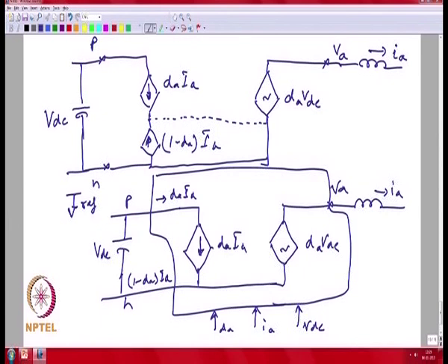And typically in control applications, you will have measurement of your DC bus voltage, you have your AC current measurements, your controller is actually outputting your duty cycle, and then you could actually incorporate a model such as this for the one leg of the power converter. So, instead of using the average value, now the value of V_A with respect to a reference is now a continuous quantity rather than a discontinuous quantity. And similarly, the currents that are coming in are now continuous quantities rather than discontinuous quantities.